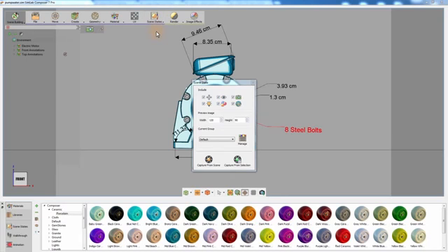Scene states allow you to capture several attributes from the scene and store them. When the captured scene states are activated, it will reapply all the attributes it stored back into the scene. To see how scene states can synergize with annotations, make sure that the visibility and camera options are included in the scene state and click Capture from Scene.